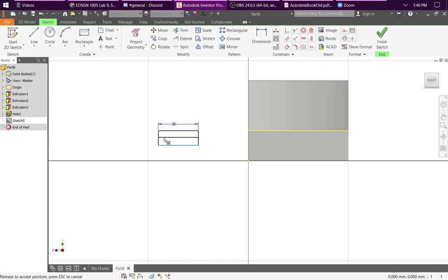All I did was click on that line and kind of dragged it away from where it had overlapped. Then I'm going to click the coincident constraint again, click the bottom corner and the bottom here. Now it's the right height that we want. I can drag it over here. It's about where we want it.